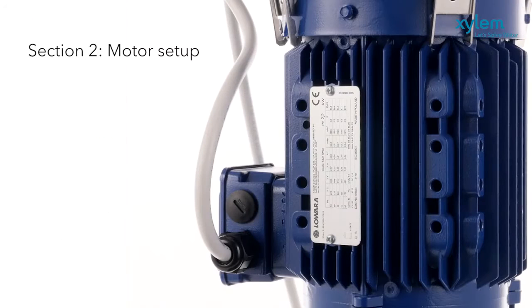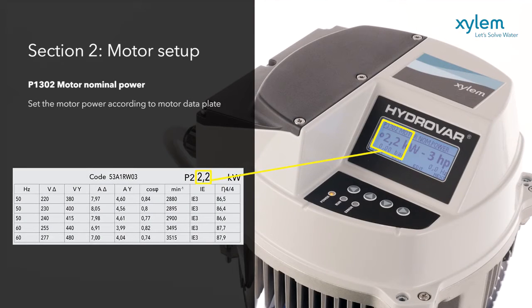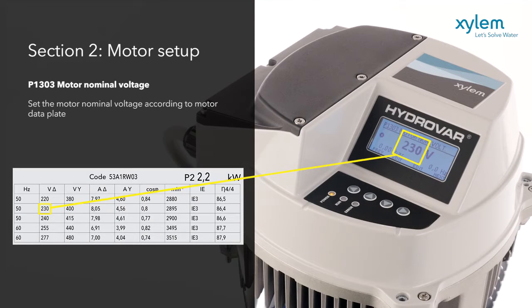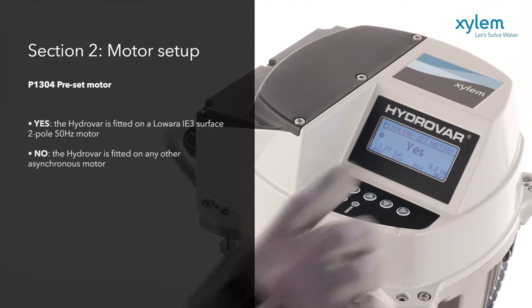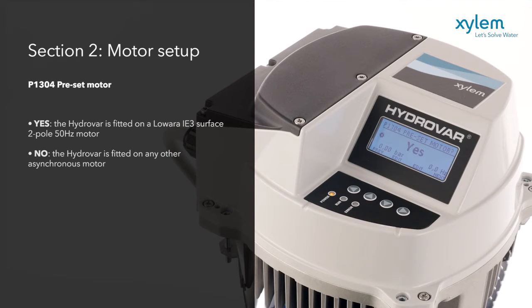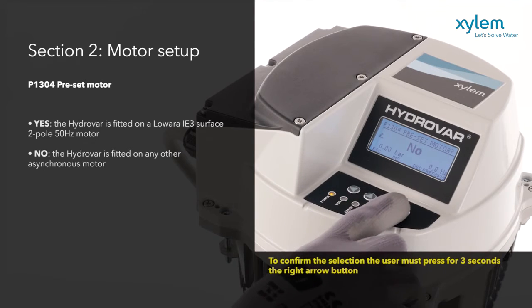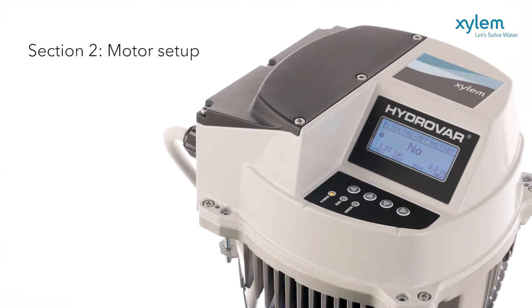The data plate on your chosen pump motor will show its nominal input voltage and the correct rated current, which you set on the Hydrovar. Or you can just select the data for a Lowara IE3 2 poles 50 Hz motor, which is already built into the software, or simply select a generic motor. If No is set, additional steps are required to let the Hydrovar identify the correct motor parameters. Otherwise, go directly to the STC thermal protection settings.